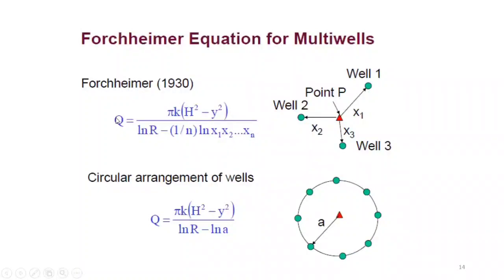Sometimes you need to know how much water will come into your excavation. Okay. So in that case, you already know the value of K, and these are numbers, so you need to know how much water will come to your excavation, so you can use this formulation. Or the other way around, you're pumping water out, you know the zone of influence range, you know the positions of the wells, so you need to know from that pumping test the K value of the soil, so you can use this expression, vice versa.